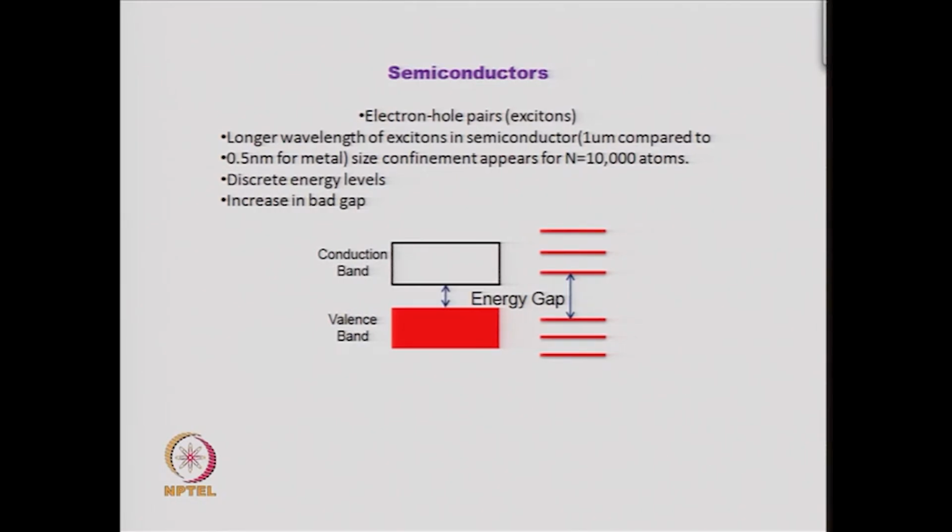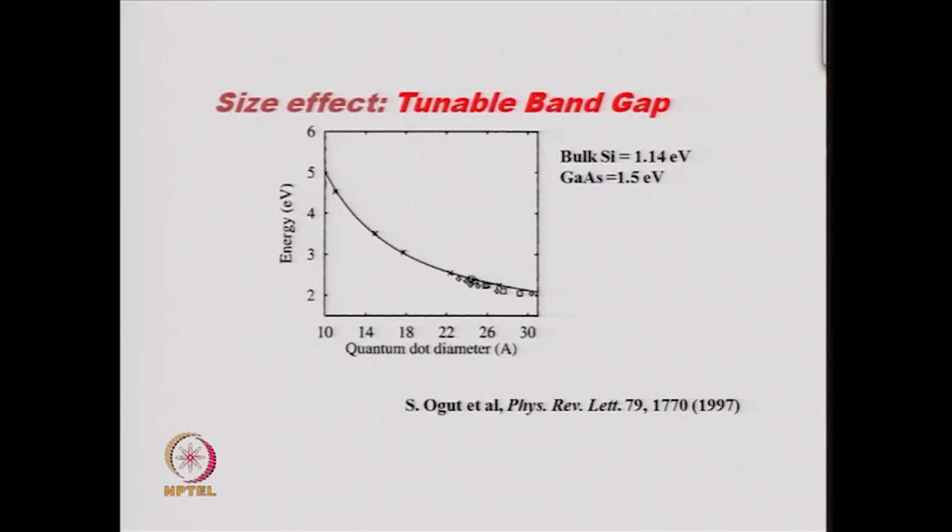An exciton is an electron and hole pair that has been created because the particle has absorbed energy which has been given, and that energy is larger than the band gap, and so an electron is excited and it leaves behind a hole in the valence band. Together the electron and hole pair is called an exciton. So, this is the basics of absorption of radiation creating excitons.